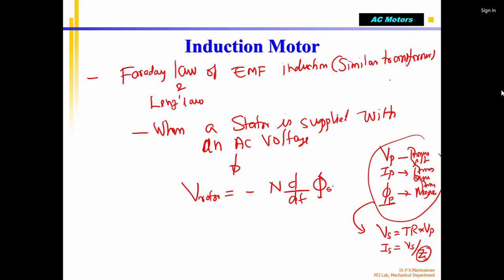Already I told you what Z is. Impedance equals the square root of R squared plus XL squared, because the coil has resistance, since it is made of resistive copper, aluminum, or some material. Also it has inductance, and 2 pi f L is the XL, the inductive reactance.